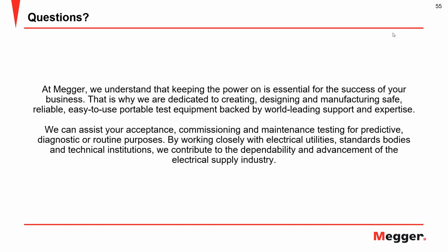So there are certainly advantages to using non-conventional partial discharge testing, but in terms of determining the condition of your insulation, the conventional method with the coupling capacitor and measurement impedance to achieve the picocoulomb measurement of discharge is certainly one of the most advantageous.